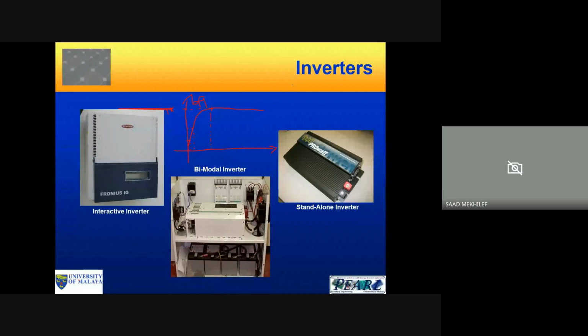The temperature is ambient, room temperature 25 degrees C, because temperature decreases the efficiency of the PV panels. That means it will decrease the voltage, because once the temperature increases, the voltage from the PV panel decreases. You know that.